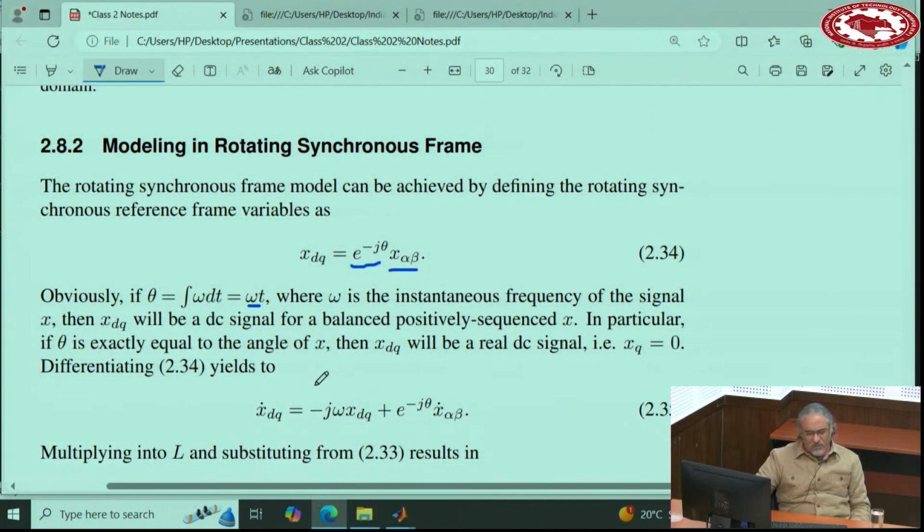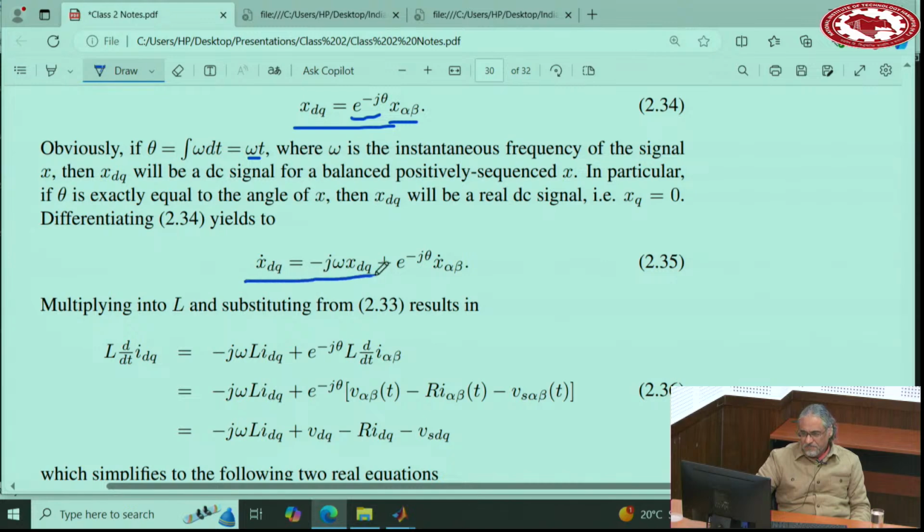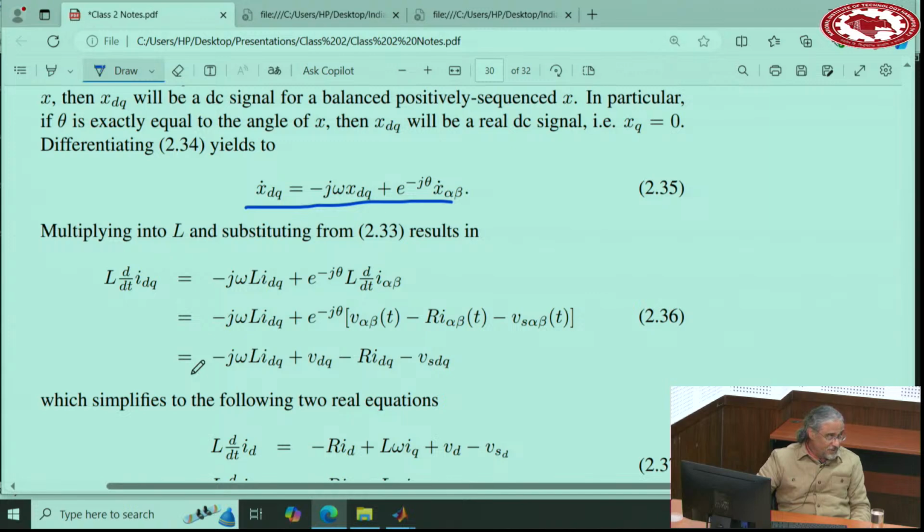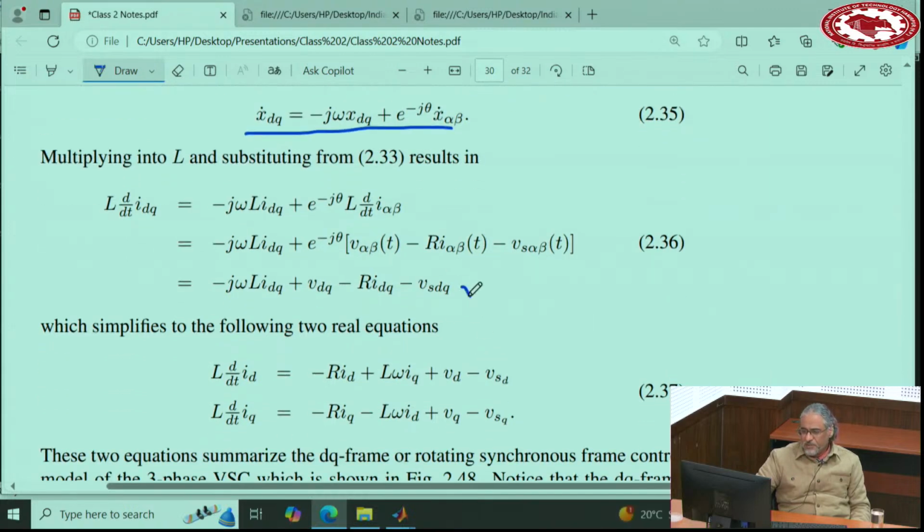However, the derivation of equations becomes a little more complicated because now you need to take the derivative of this equation and then go back and derive the equations. Do it when you get home or in your room tonight. Then we derive two equations. You can represent them here as one single equation or two separate equations. We call them D and Q for these new directions. Both of them are not rotating anymore. So XD and XQ, or ID and IQ.